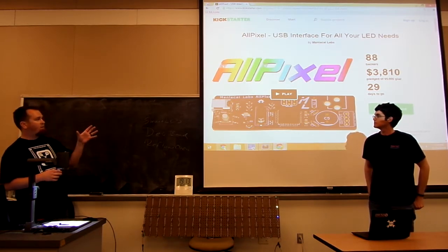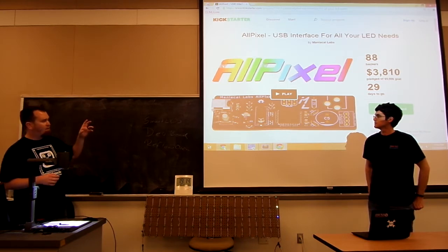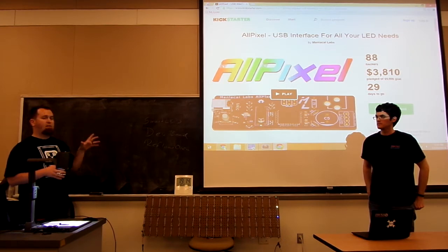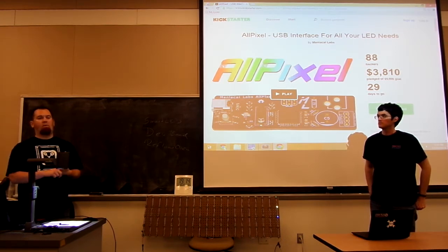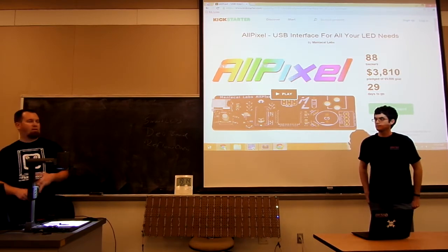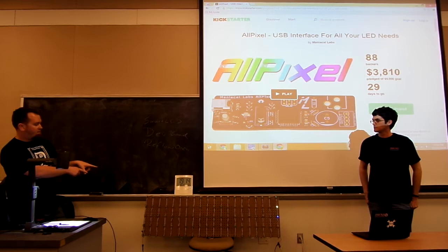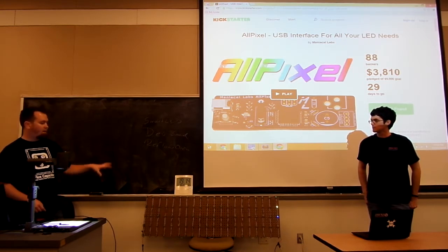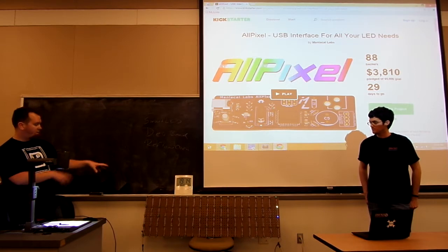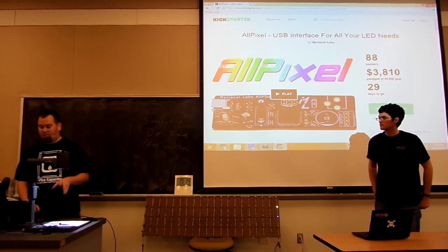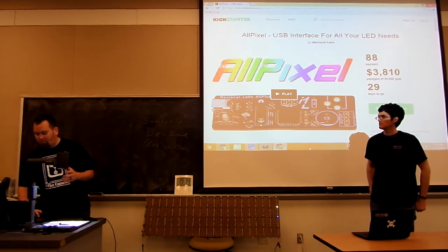So it's called the All-Pixel, and it's based on the ATmega32U4, and it can drive 8 different LED strip types, 3 of which are the major ones that you generally hear: the NeoPixel, the WS2812, WS2801s, and the LPD8806. This is a display that Dan made for just a demo. That's the WS2801, sort of the Christmas tree style lights. I was just going to show you a quick demo.